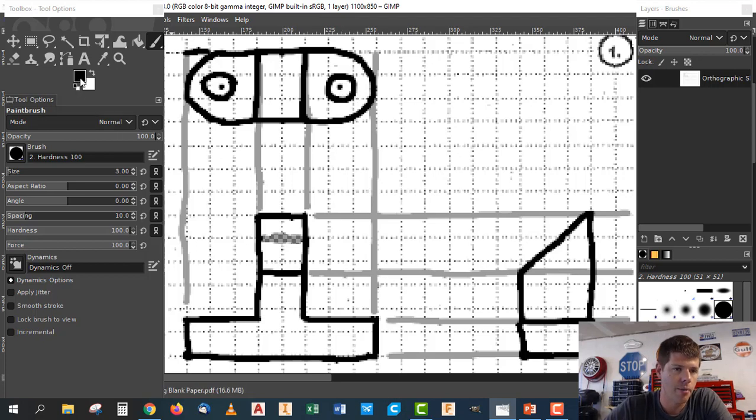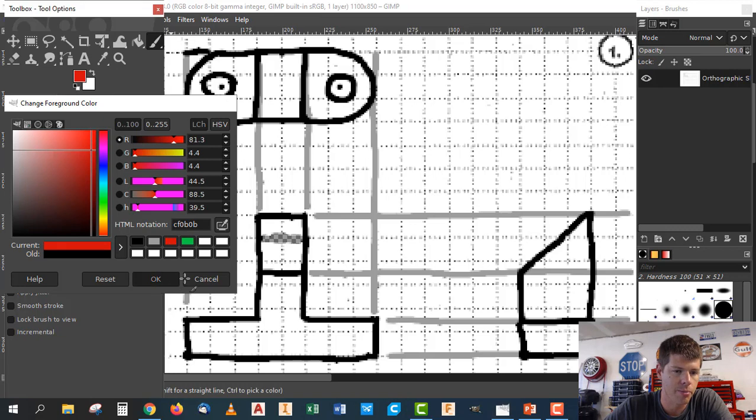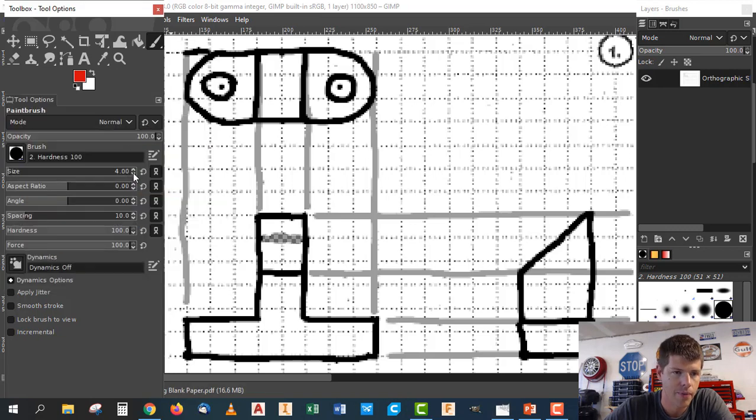Now what we do is we grab our other 2 colors, let's switch to red, and we're going to put in some hidden lines. Okay. So these are things that we know are there, but we can't see them. So really the only thing we have to worry about for this is the holes. So if we look, we know these holes go through the base, and I'm going to go straight down, and I know that they're going to go here and here, like the sides of the holes, and here and here. And I'm going to put in dashed lines for those.